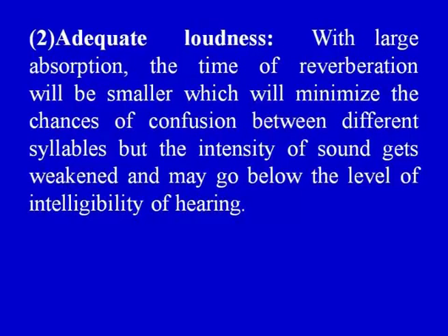Number 2, adequate loudness. With large absorption, the time of reverberation will be smaller, which will minimize the chances of confusion between different syllables, but the intensity of sound gets weakened and may go below the level of intelligibility of hearing. Sufficient loudness in every portion of the hall is an important factor for satisfactory hearing.